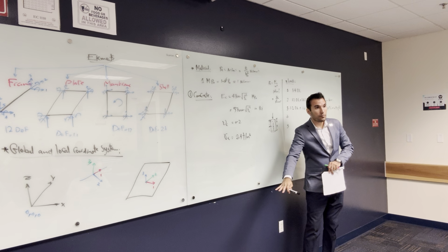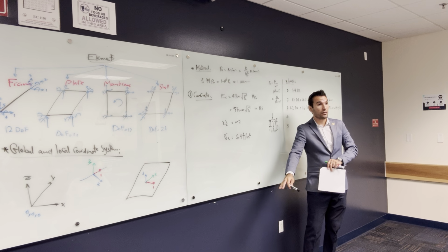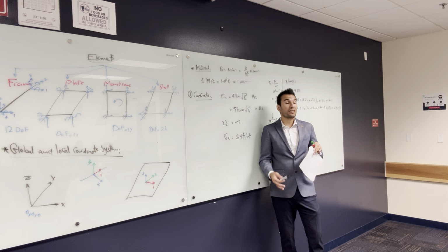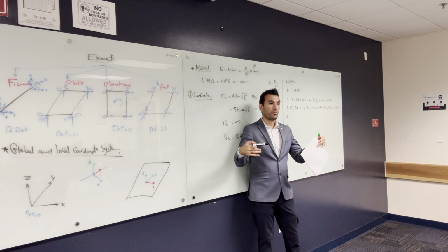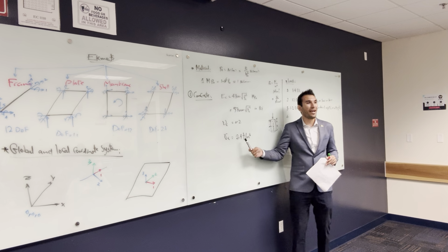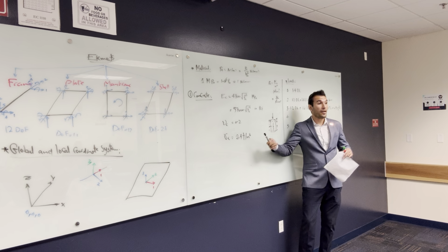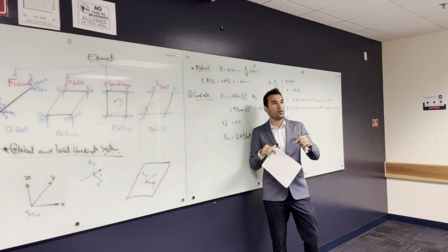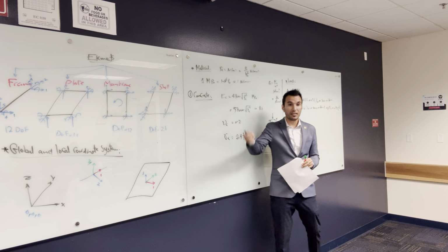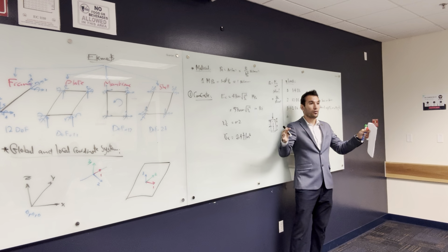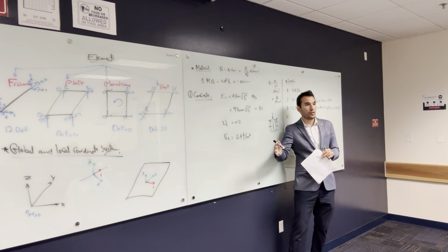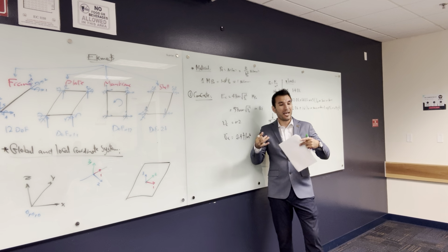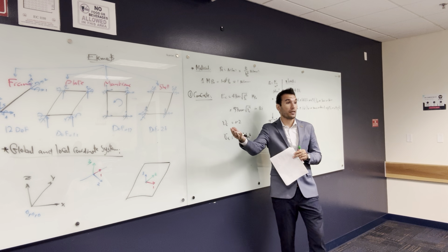But for the slab system, you don't need high strength concrete. You need regular strength concrete and maybe lightweight concrete. You know why? Because it helps us reduce the loads on the column. Rather than having a density of 2.4, I'm going to have a density of 2 or 1.5. By the way, the slab is the main load on the whole structure. The columns themselves weigh 10% of the structural load, and the slab is 90%. If you are able to reduce their loads, you are going to reduce the load on the columns and reduce the cross section of the column and then save money.